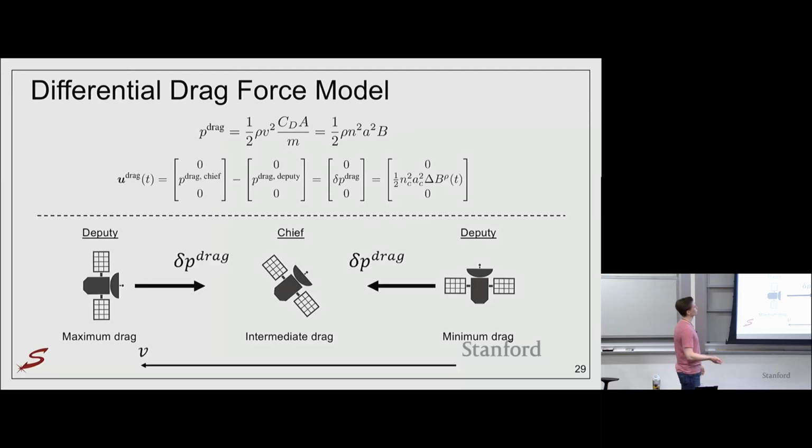And the kind of force model that we're going to be using here is given here, where we have a very standard force of drag equation up there, assuming near circular orbit, assuming orbit averaged atmospheric density, assuming that the force is completely tangential in the Chief's RTN frame. And also, as I've been called out a couple of different times at conferences, assuming that the relative velocity between the spacecraft and the atmosphere is the spacecraft's actual velocity in near circular orbit.